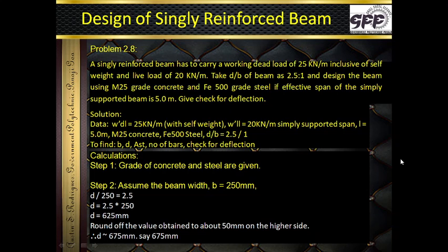Also notice another thing, the beam is a simply supported beam. Its effective span is already calculated and told to us to be 5 meters. We have also been told that there is UDL in the form of dead load, in the form of live load. And please note, when it is not mentioned on how much portion the UDL is, we assume that it is over the full span. So UDLs are expected to be applied on the full span. So let us go ahead with the solution.